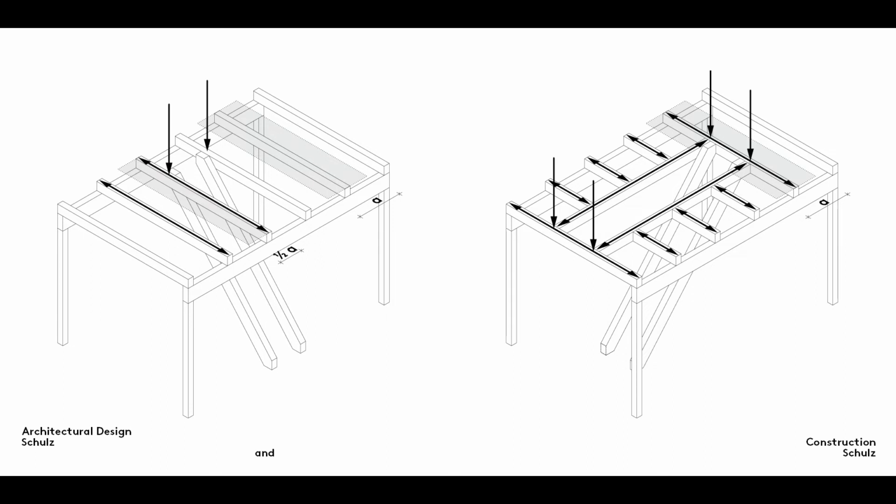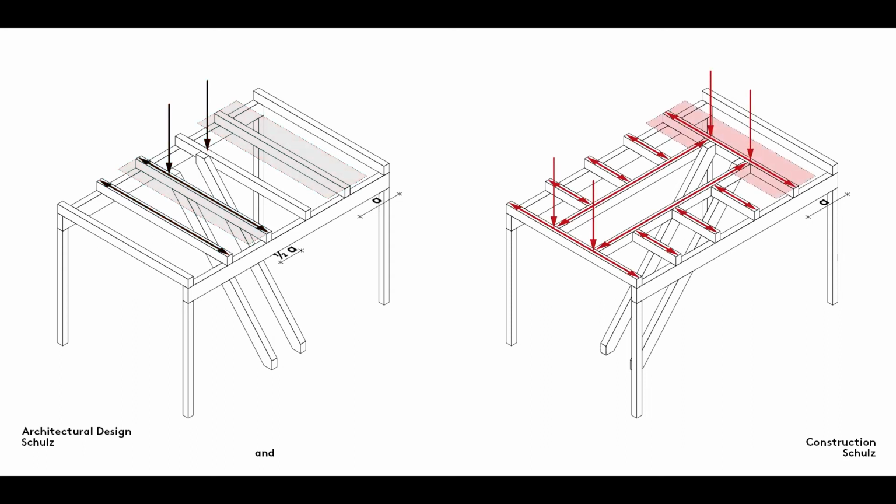The parallel stairs are easy to fit since, though the joists on either side of the opening have to absorb the point loads from the stairs, they have only half the tributary area of the other joists, and there is therefore no need to change their dimensions. The stairs at right angles, on the other hand, require the load to be diverted via trimmer joists that once again transfer high point loads to individual joists. As a result, the joists will have different dimensions.